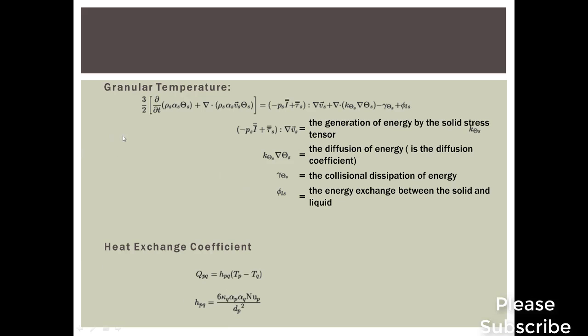So that is called granular temperature. I have already said, that is theta s. For that theta s, we need to solve this set of conservation equations, which is an extra burden to our regular solving capacity. Regularly we will solve one momentum equation, one continuity equation, one energy equation. But now here we need to solve two momentum, two continuity, and two energy. Apart from this, we also need to solve the extra granular temperature equation in order to know